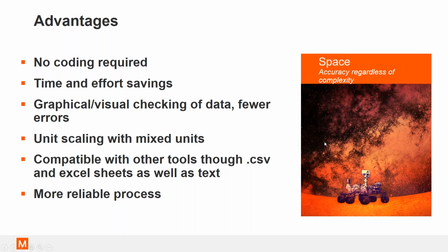Also, this field capability is tool agnostic, as long as the tool that you want the data coming from can export the data in a CSV file, so comma separated values, or as a text file, you can import it into Simcenter. You can also use Excel sheets directly to modify the data or simply copy paste the data into Excel. All these things make for a much more reliable process than having to hand code something or to include interpolation cards into an input file for your solver.